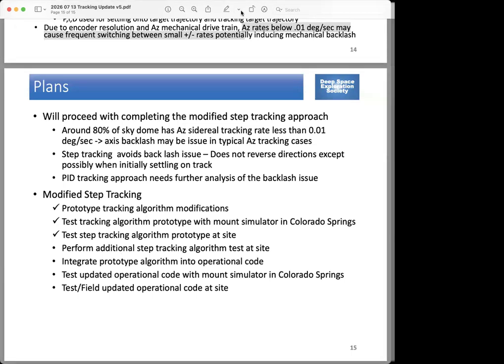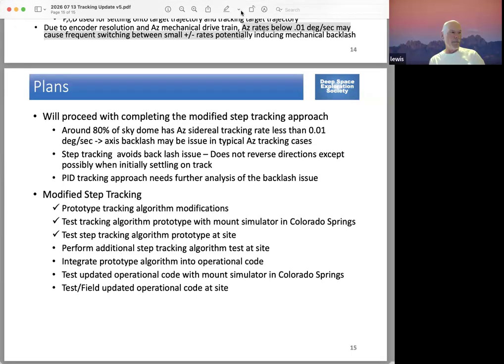And another thing, not an issue, but it was mentioned: the temperature when you run the motor at slow speed. It needs ventilation. So it makes sense to also set up a temperature sensor on the motor just in case, for fire safety and for motor safety. Yeah, I'd have to go back and check the thermal controls on the controllers. I'm not sure if they'll shut it down when it gets too hot or not. I need to look at that.